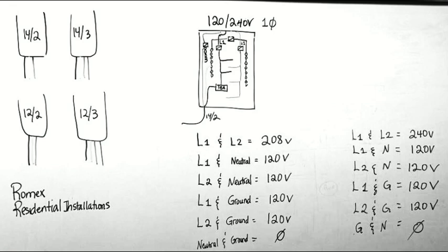Because when current is flowing through your wires, they're creating heat. And if there's a little bit of air in between, for example, when you connect right here to these screws, I always make sure that the wire can't move. This connection right here has to be very tight, because if there's a little bit of air, there could be arcing created. And that arc allows a lot of current to flow. Instead of only 0.89 amps flowing through here, that might go up to 6, 7.